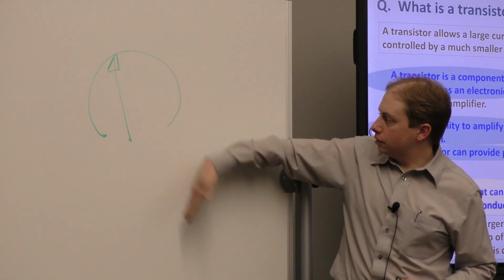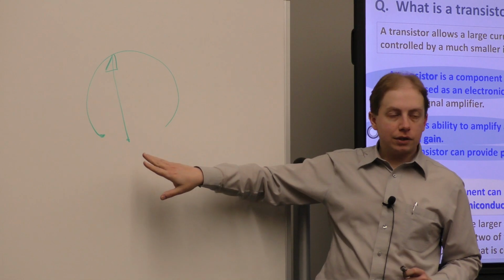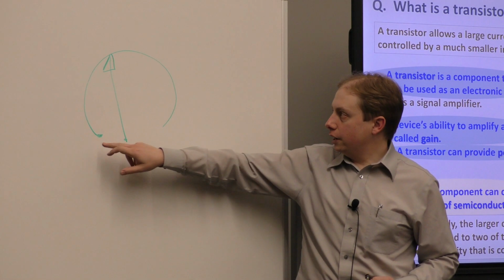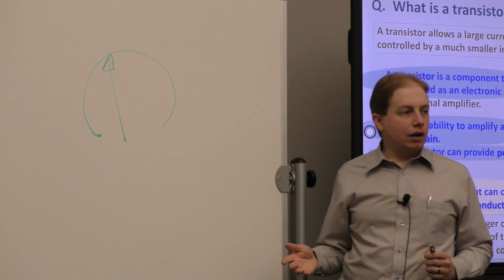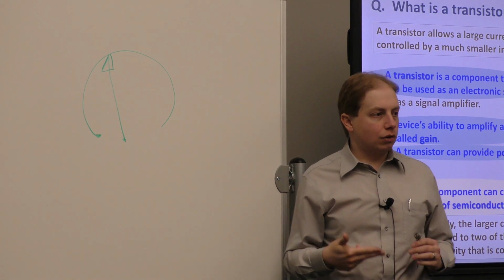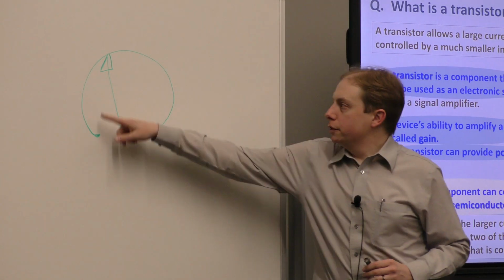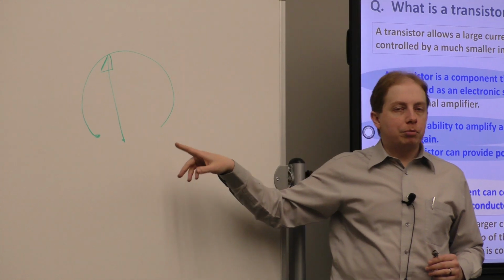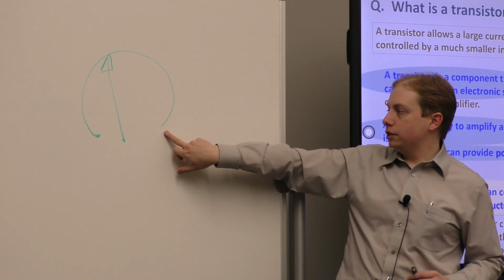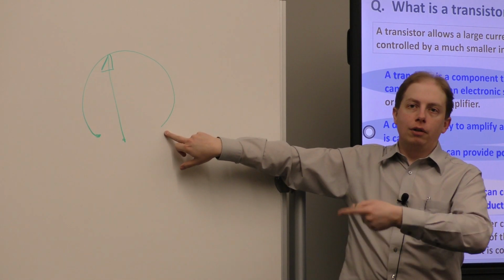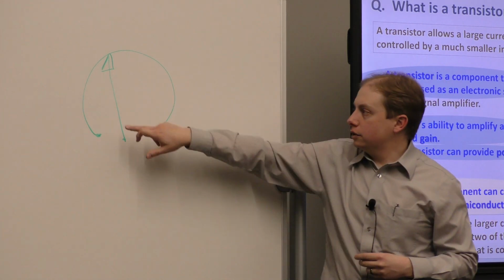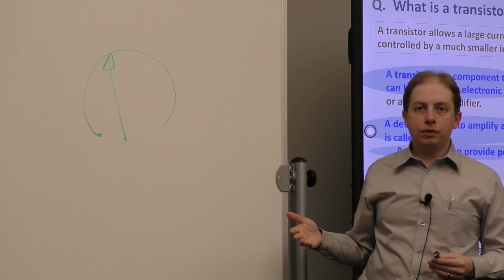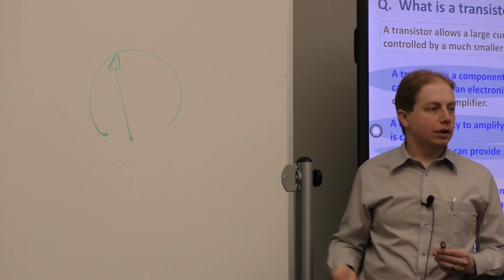If you eliminated this and you just had a rheostat, you put a voltage here, if the input stage of the amplifier doesn't draw much current, moving this wiper doesn't really do anything. Because even way over here at full resistance, because there's so little current flowing through the circuit, this resistance is negligible and you don't get the variable gain effect that you want.